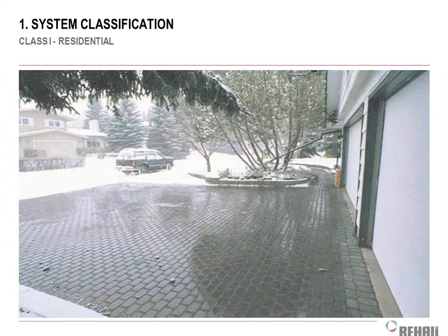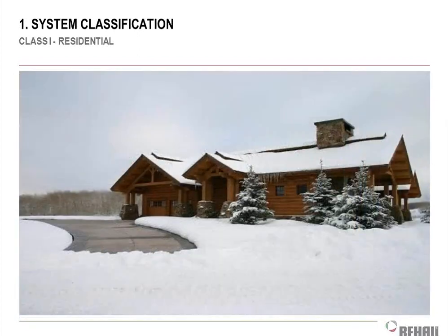By the way, you also got to think about drainage, right? These driveways need to be sloped away from things you care about, like your garage. So this one's sloped towards the street, so that's good. And probably the reason they did it is because they got this brick layout, and if they were shoveling, snow blowing, or plowing that, it would probably rip it up pretty good, and the salt would get in the cracks and rip it up pretty good.